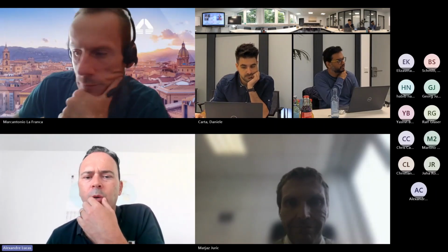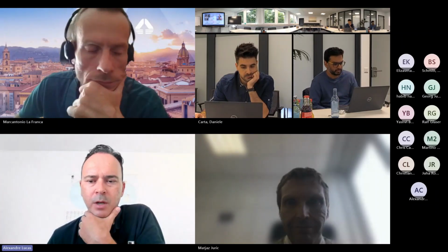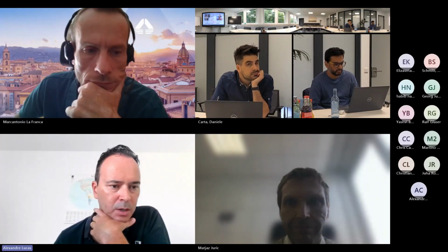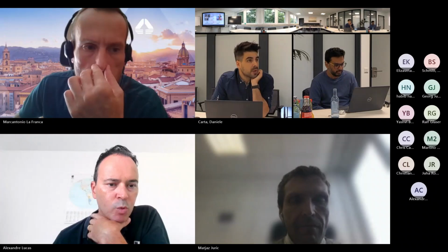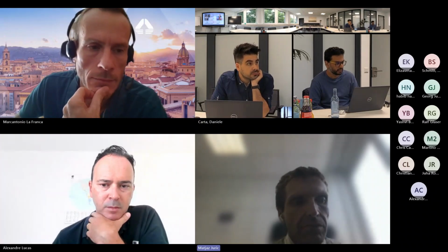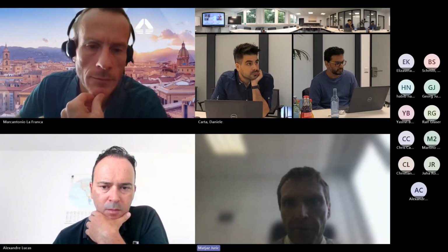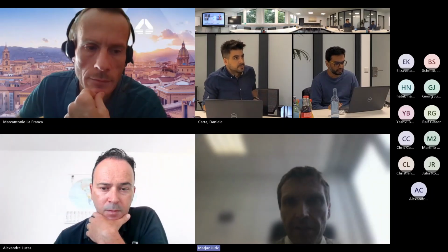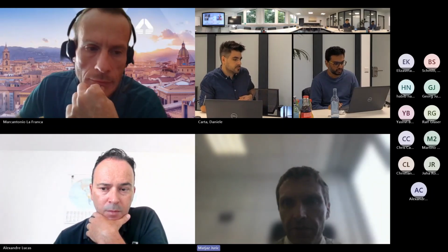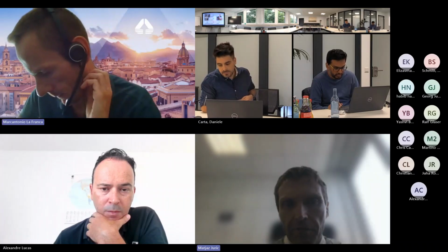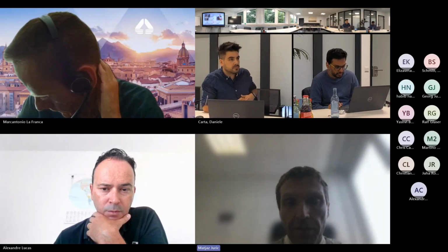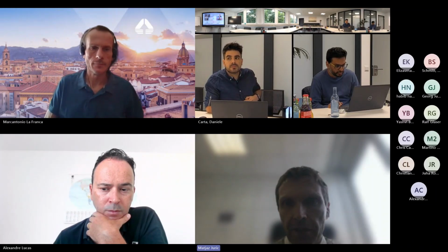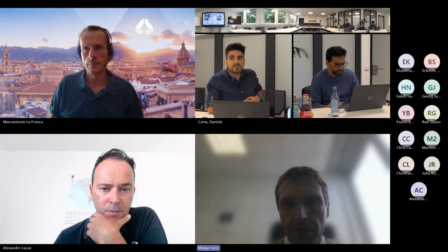We have here, how does one know that the semantic description of the monitoring and control variables is well done with a legacy protocol conversion? Does the tool help? Yeah. You have several options to test the conversion. Once you specify the conversion, you can do some test runs with sample input messages, and you can see the output messages on the console or in the log of the legacy protocol converter, where you can verify them. Also, the legacy protocol converter has an option to validate the IEEE 2030.5 conformity of the messages.